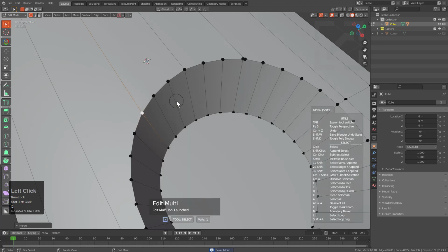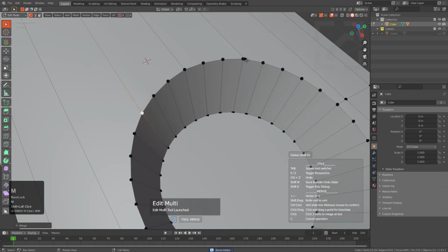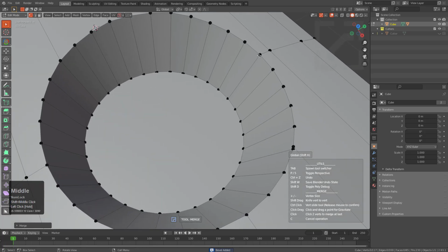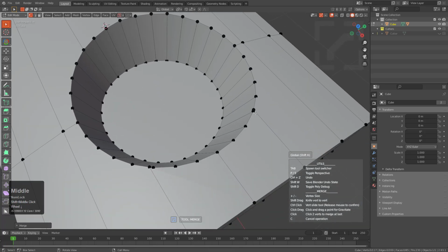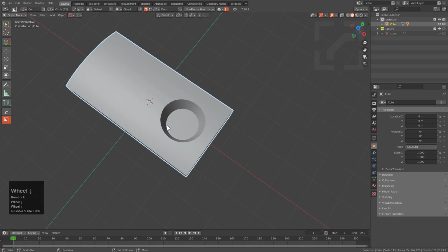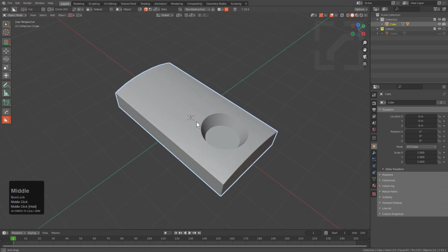We could shift click mark, press M to jump over to merge tool, and actually just drag any points that look like they possibly have a straggler nearby. Press C to cancel if you end up accidentally selecting the wrong point, and I believe that actually does it. So by keeping the geometry pretty sparse, it's easily controllable.